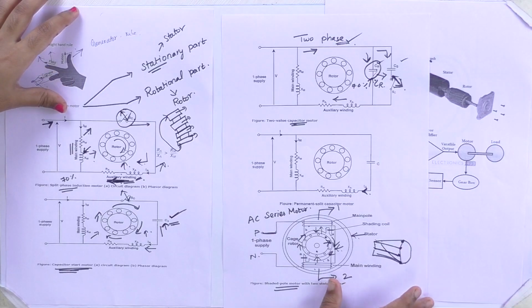Because of that, your fan will be rotating very slowly, or excitation will take slow. Sometimes your fan will not rotate, it will only give a vibrational sound. Why it happens is that the capacitor start condition is not achieved in that, so torque will not be achieved. This is the simple example I am giving for the single phase induction motor of split phase type.